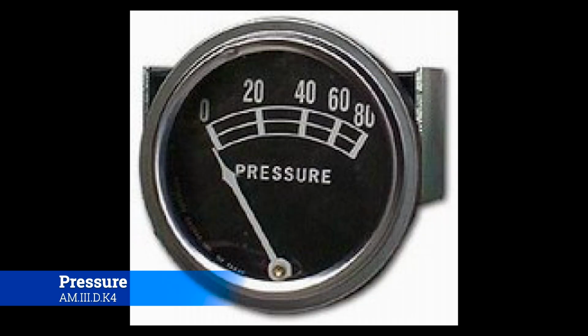Okay, oil pressure is another big one. Oil temperature will tell you the health of the oil. Oil pressure, a lot of times, will tell you how much oil is actually there. If you have a lot of oil in there, the pressure generally goes up. If you have a low amount of oil in there, the pressure generally goes down. A lot of times you can see this interplay. As the oil pressure falls off, oil temperature comes back up, generally speaking.